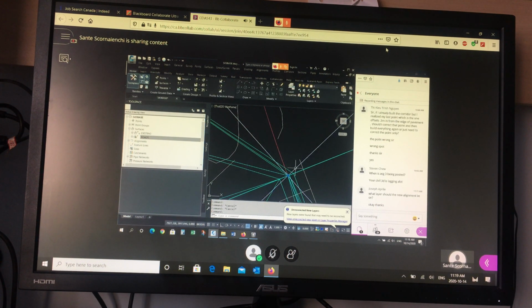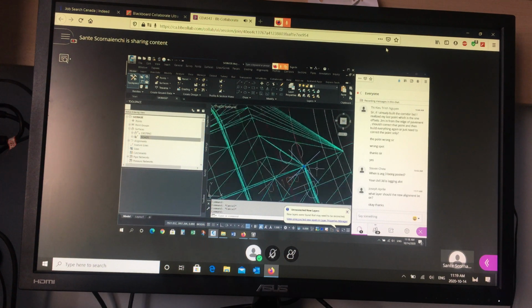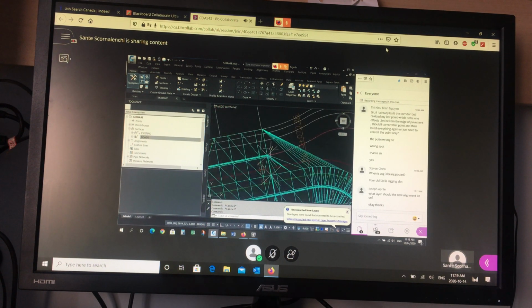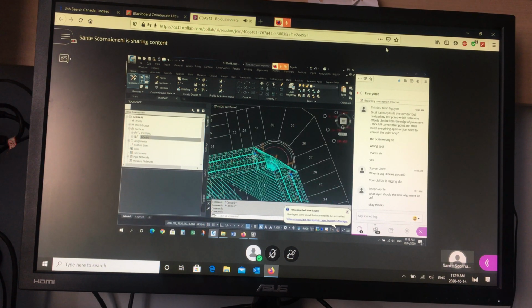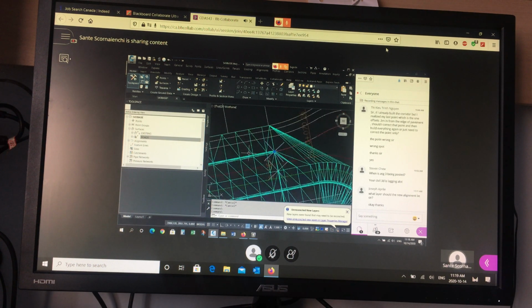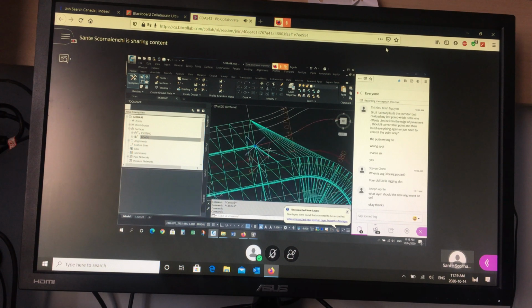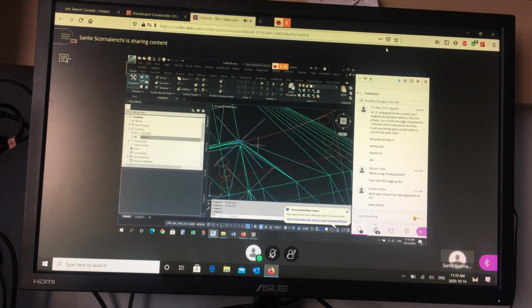So that's what the elevation is right now on this surface, right? It's correct. Everything in between is garbage, but the station, which we already established, is correct. The elevation of this surface at those two locations is actually the elevation I want for my profile of the gutter. So now I'm going to do something a little different.